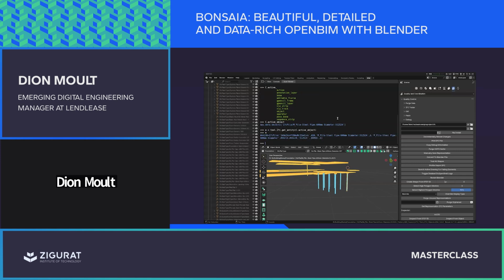And now we have our IFC pile. And I can write all sorts of scripts quite easily. So I can say, get me all of the properties of this element. And in this case, it's given me the properties as a nested dictionary, or I can say, give me all the materials of this element. In this case, it's made out of steel.